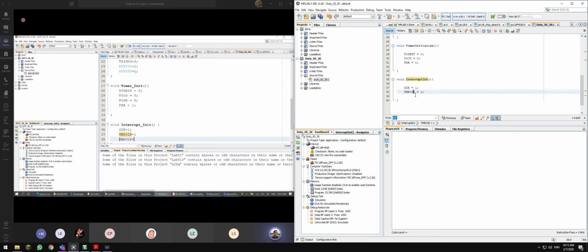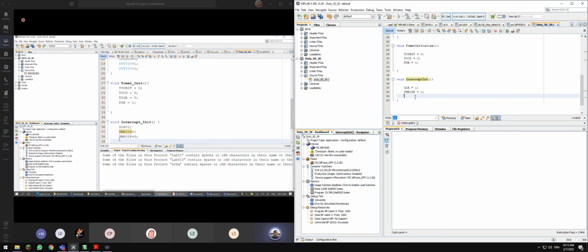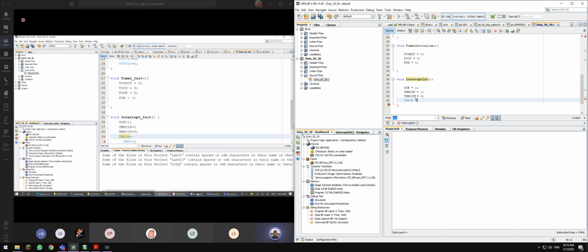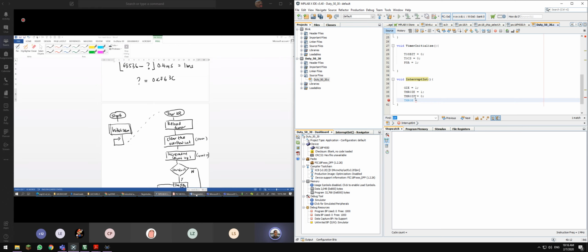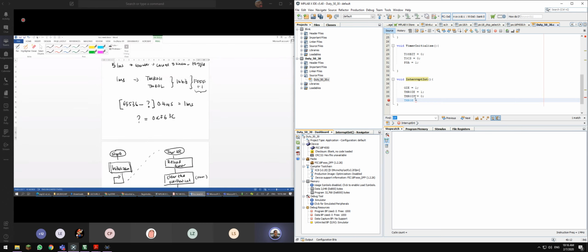Then same, we reset the overflow flag, just for safety purposes. Then we have a timer. Just now it is Timer 0. TMR0 high, is it? Timer low. So what is the value just now? We have the value that we have calculated: 0xF63C.